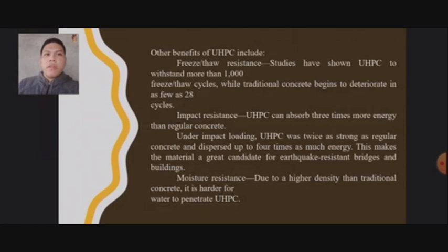And other benefits of UHPC include freeze-thaw resistance. Studies have shown UHPC to withstand more than 1,000 freeze-thaw cycles, while traditional concrete begins to deteriorate in as few as 28 cycles. Impact resistance: UHPC can absorb 3 times more energy than regular concrete.